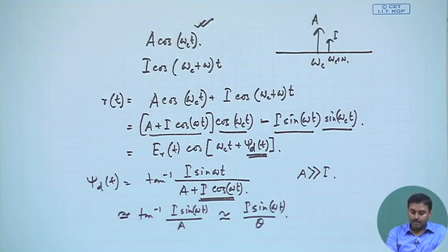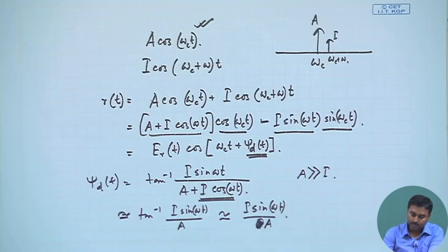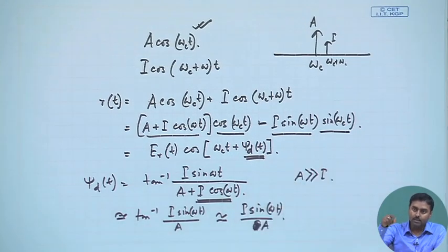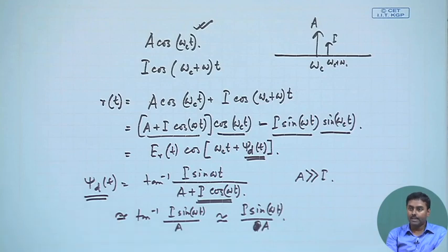Okay. So, the FM modulated signal and the phase part of that. When we demodulate it, what do we do? We take the phase and we differentiate it. That will be the frequency, and that must be my signal. That is how FM demodulation goes. It detects the phase and then differentiates it. We have already understood that, because in the phase it will be an integration, and then you differentiate it to get the overall phase. So, here also, because it is an FM demodulation chain, we will employ the same thing. This particular phase will be differentiated, and whatever we get is my received signal.